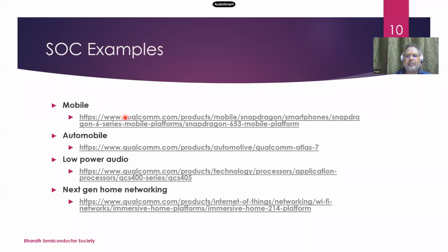So what is unique about this chip is that about 6 years back, there was a need to support 8 GB of memory space in the system. But the bus interface was 32-bit. The backbone bus interface I mentioned, the XA bus interface, could support only 4 gigabytes of memory. 2 raised to 32 is 4 gigabytes. You can do the math, right? So it supported only 4 gigabytes of memory.